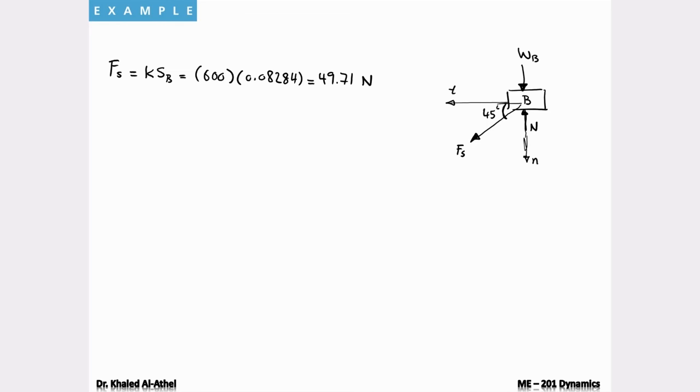Now, looking at the problem, since we need to find the normal force, when I do summation of forces, I'm going to have an acceleration. Normal force appears in the normal direction, therefore I need the normal acceleration. If you remember from kinematics, this equals v squared over rho. V, I just computed previously, is 5.127, or 5.13 if you want to approximate, over rho, which is 0.2.